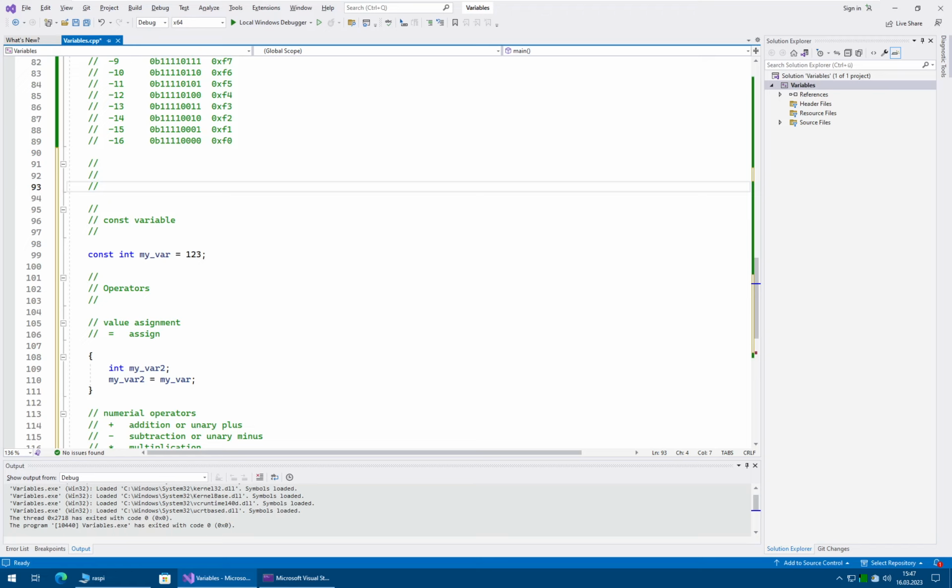The C or C++ compiler will abstract these away from you. So even if you have hardware which does not support floating point numbers, you can still write your code with floating point numbers, and then the compiler will just implement an integer implementation, or rather use a library that does this already, and allow you to use all the floating point numbers you might ever want to use.